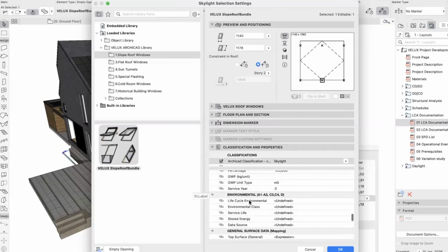So there's also the material CO2 report. So let's just load that. It will take all materials that are used in the model. It will calculate some of them from cubic meters, some of them for square meters, and some by kilogram, and again show them here. It's divided by the layers materials are modeled on, and then in each material. So when I scroll down here, there's a lot of materials.